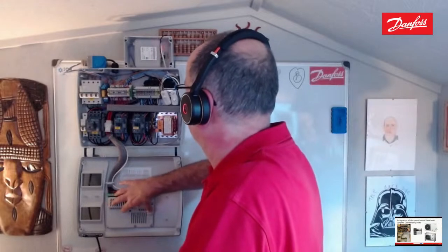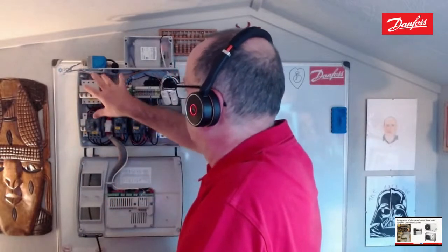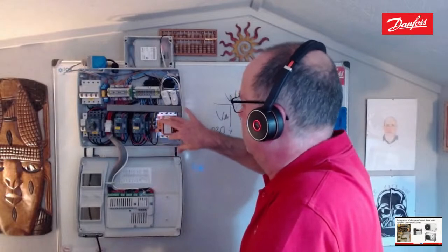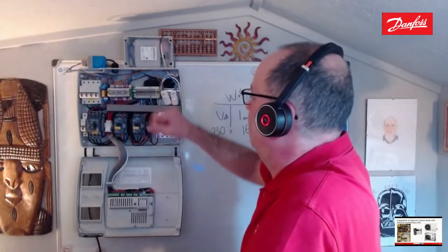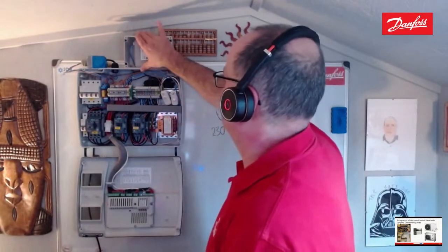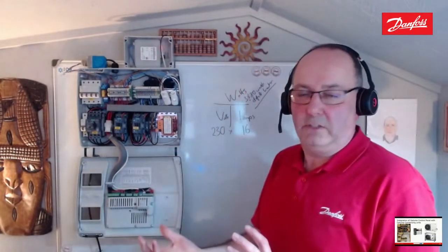The evaporator fans are not that big. Because this is three-phase, I've just wired it as single. We've got a transformer in there to separate out the control voltage to 240 from 415, which makes things a little bit safer. As I said, we've got the Prosa device up here, which is monitoring the temperature in my office, and we'll see that a little later on the slides, or I can show you on the phone.